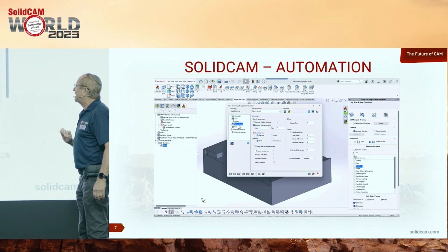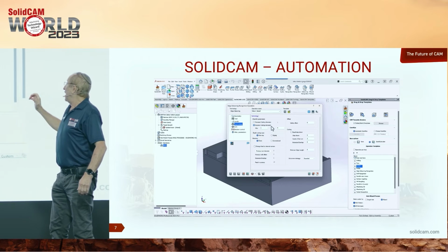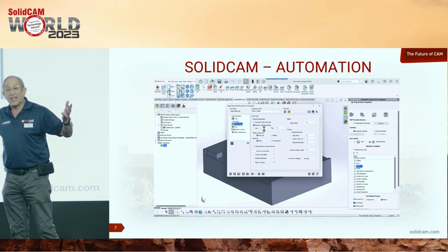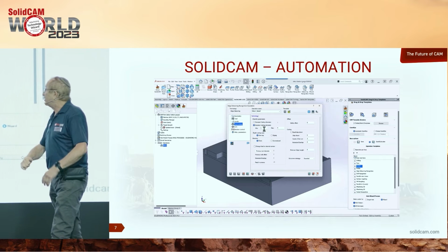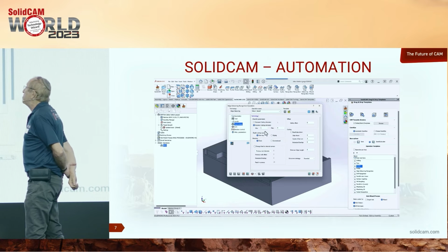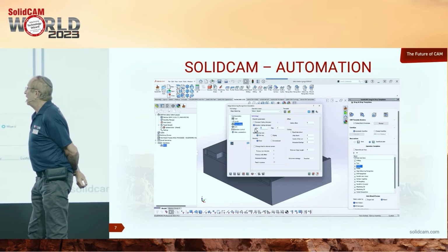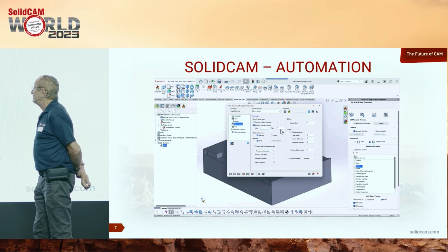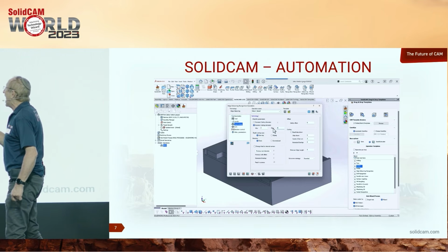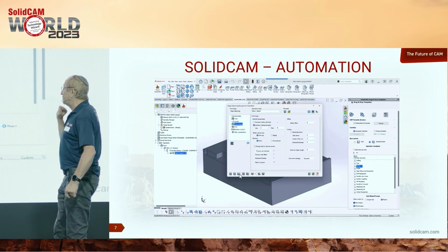Now, let's go into our technology field. As you see, the dynamic cutting diameter is set right now at 1 to 4, but the maximum could be up to 10 millimeters. And the minimum as small as that particular tool is. But you want to stay up off of that tip a little bit, right? Right, exactly. So let's go into our minimum diameter. I'm going to set it at 2 millimeters for the minimum. You don't want to go that high on the big diameter either, right? Now, my maximum is 10, but I don't want to go that high, so I'm going to set it at 8 millimeters. Very good. I'm going to save and calculate, and let's take a look at the simulation, okay?